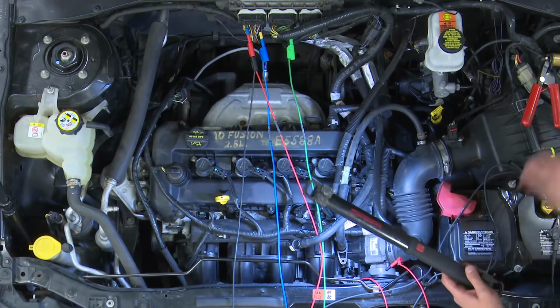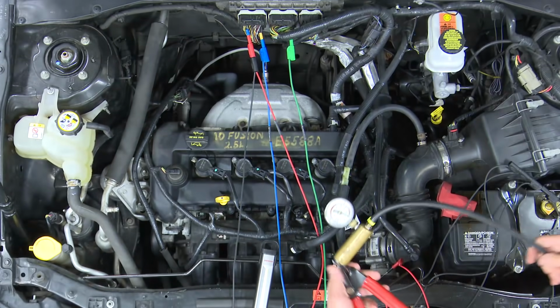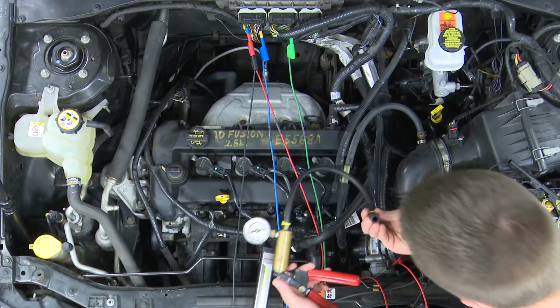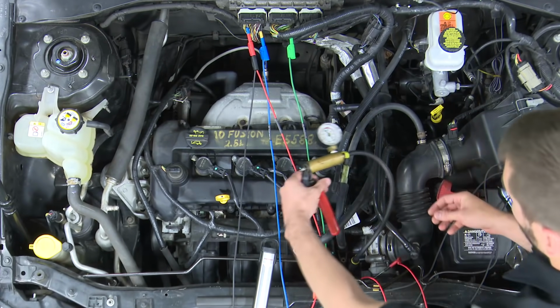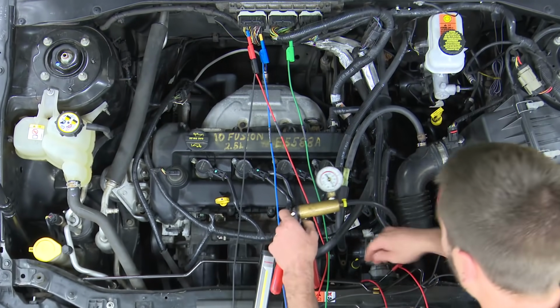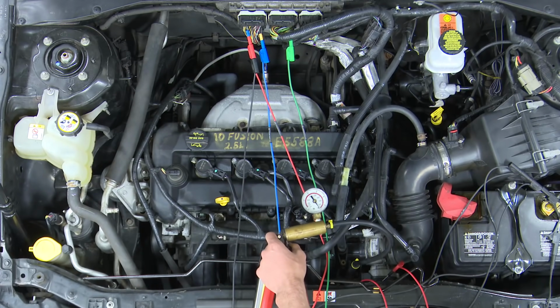But what I'm going to do now is I'm just going to do a quickie check on this thing. Got a vacuum gauge or a vacuum pump. You could use a gauge, whatever. I just have a pump here that I'm using as a gauge. I'm going to throw the hose over the canister side of the purge, and I'm going to have Fritz fire this thing up. And we should not see any vacuum on this unless the computer is commanding it. Yep, go ahead.